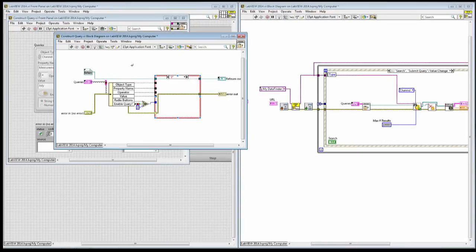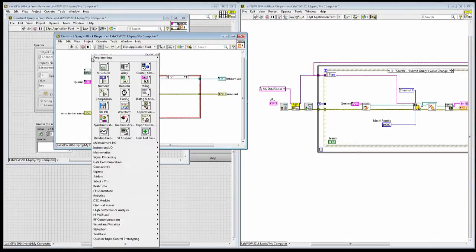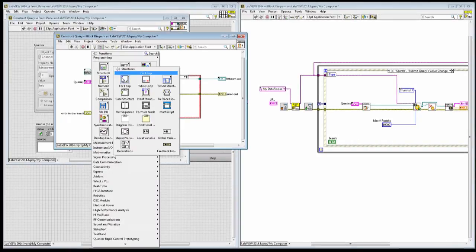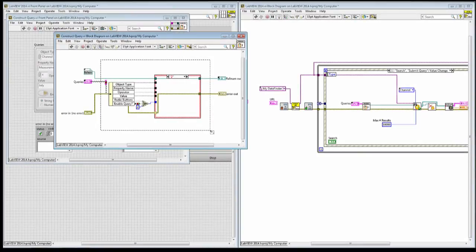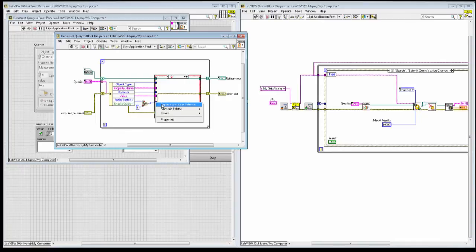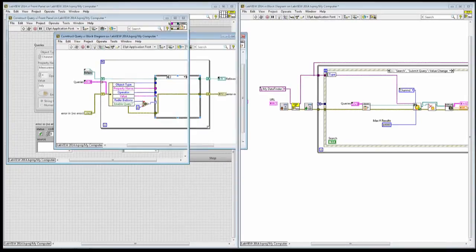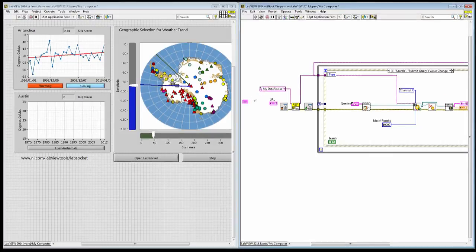Here, we can use two new enhancements that will certainly make my life as a LabVIEW developer better. The first is a smarter For Loop, which knows when to auto-index to create outputs and when to create a shift register. The second is a new right-click option in the Case Structure, which allows me to easily change the input to the case selector terminal. These are common tasks that require extra clicks.